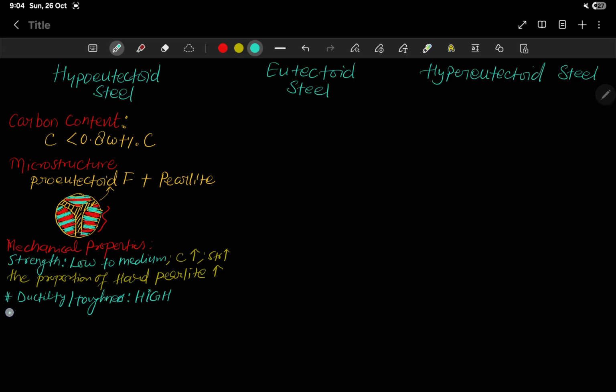The funda is, you can see here the continuous network of ferrite, which is soft in nature. When there is compression on this phase, this ferrite phase will deform properly and undergo high plastic strain or plastic deformation. So these materials are highly useful for energy absorption applications.